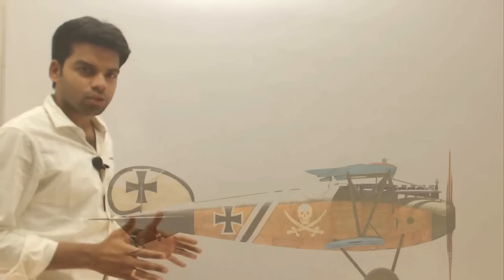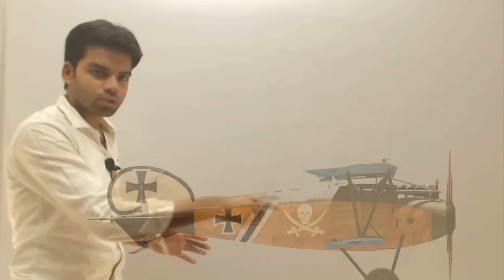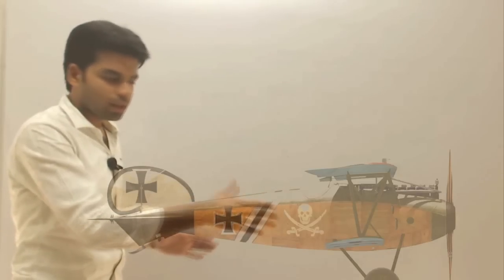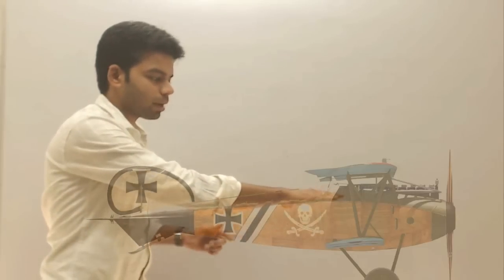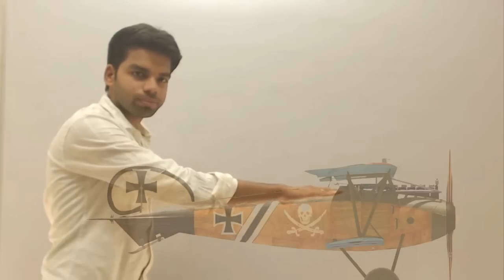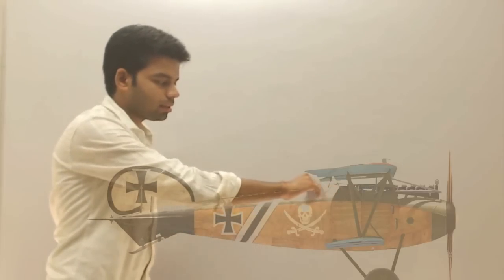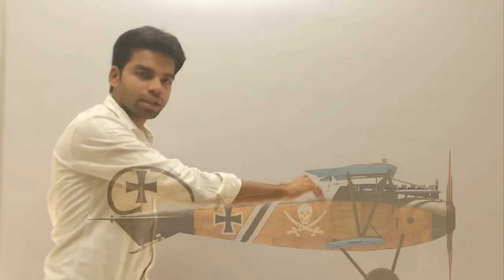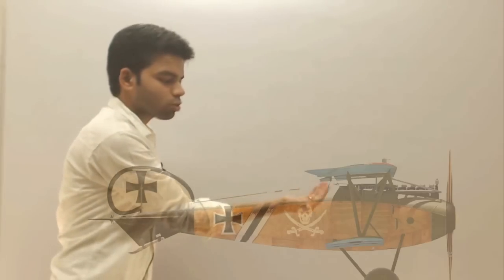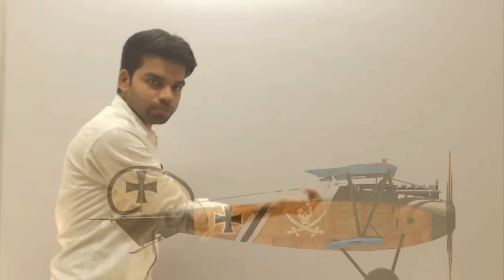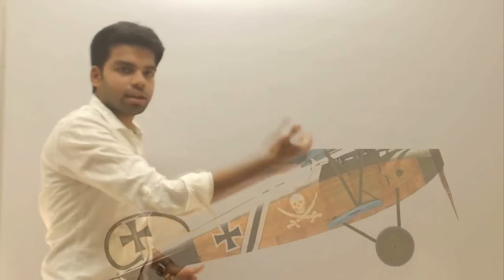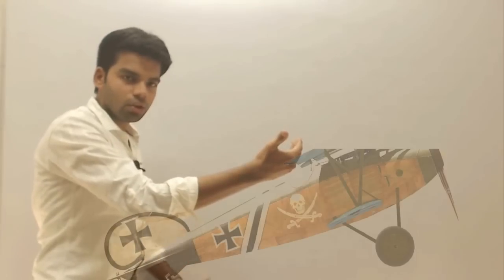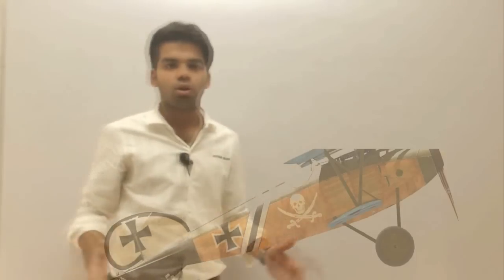So let's suppose the rotor of this aeroplane is rotating in a clockwise direction. When this aeroplane is taking a left turn, the angular acceleration will point in this direction. The active gyroscopic couple will act in the direction of the fingers curled. The reactive gyroscopic couple will act in the opposite direction. So because of this reactive gyroscopic couple, the nose of this aeroplane will rise and the tail will lower. So this is the effect of gyroscopic couple on turning of aeroplanes.